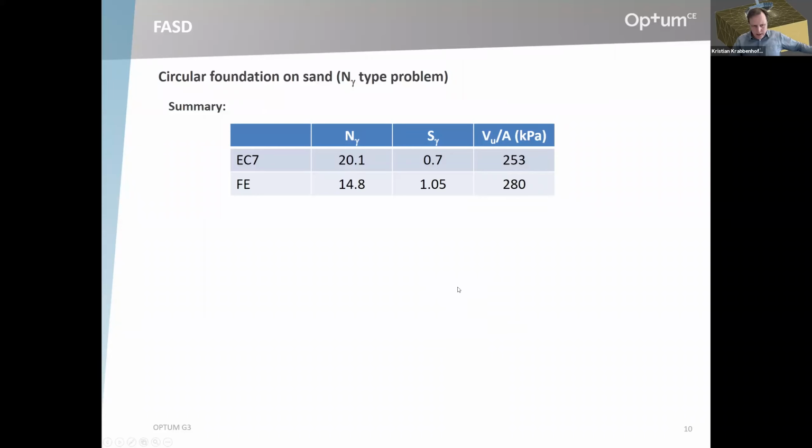But then there are people who say that actually, when it comes to the bearing capacity equation, we have made a mistake already. Because they say that N gamma should be calculated on the basis of the plane strain friction angle. So I just mentioned a generic friction angle of 30 degrees. I didn't say whether that's plane strain or triaxial or whatever. So we should be aware of what angle we're using, and we should use, when calculating N gamma, the plane strain angle. The idea, of course, being that the bearing capacity, like pretty much everything else in geotechnics, was developed with reference to plane strain. So it makes sense to use the plane strain angle.